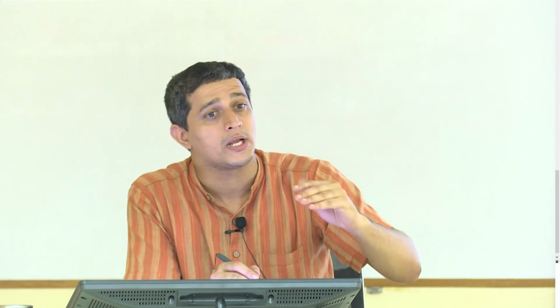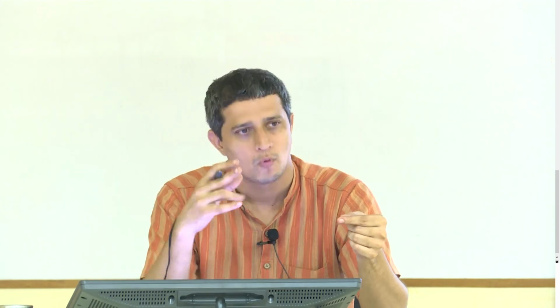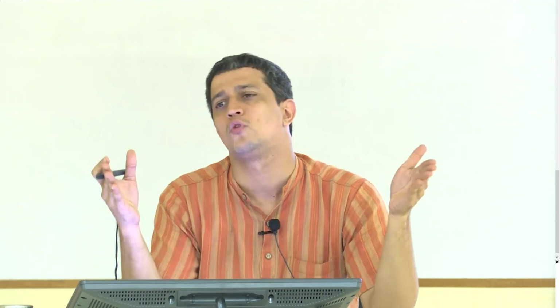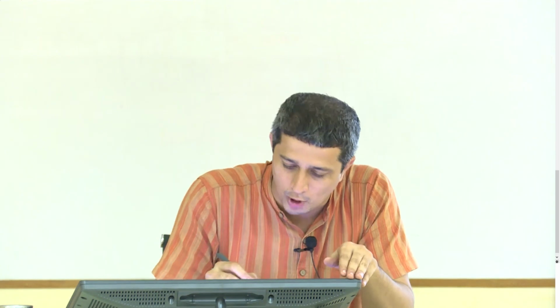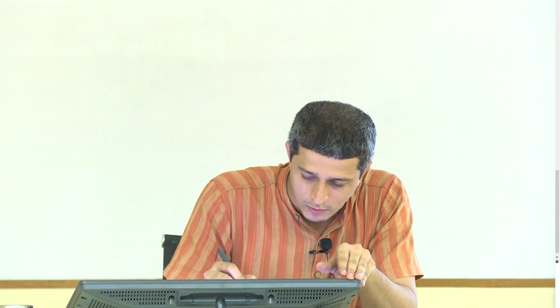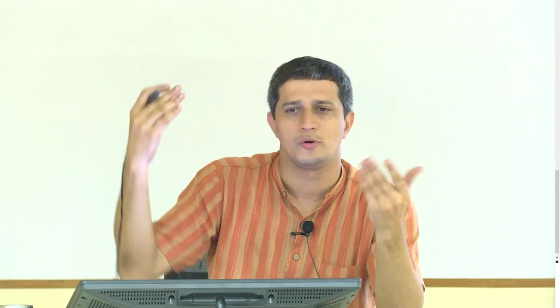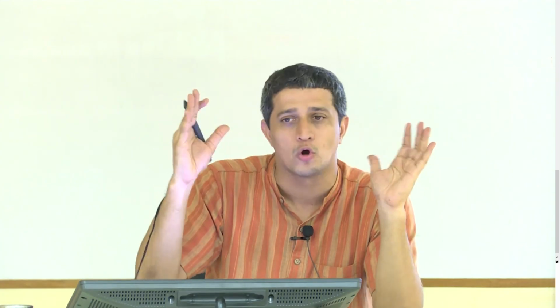The change that is happening after the sampling edge, I don't want to be captured. I want that to miss. I want it to retain D2 all through, right? So the point is, this change is T hold. If it changes far away from the edge, then D2 will be captured, there's no problem. The change to D3 will be ignored. If you bring it very close, that minimum time after the clock edge where a change in D will not go through is defined as the hold time.